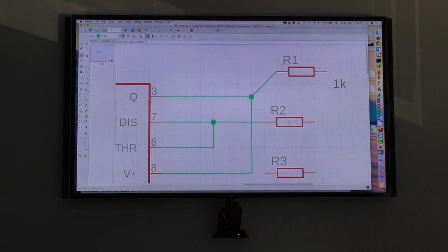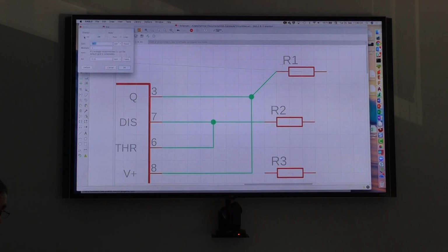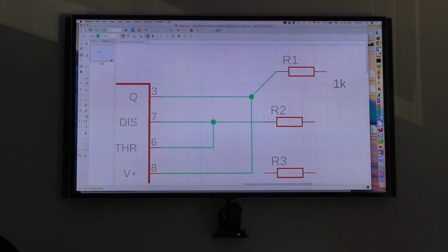Now it jumps in my 2.54 millimeter grid. You have seen in the, let's go into the grid icon, style, you see we have an alternative grid set here. I can switch it to millimeters, doesn't matter, it's a tenth of the usual grid. You can set it whatever you want to. But I can use this alternative grid. I have this text jumping. Now I use one of my fingers and press the Alt key, and now this jumps in the alternative grid, and I can place it wherever I want to. So it's a bit for fine adjustment, for example. I simply put it there. It doesn't make sense, but just to show you.